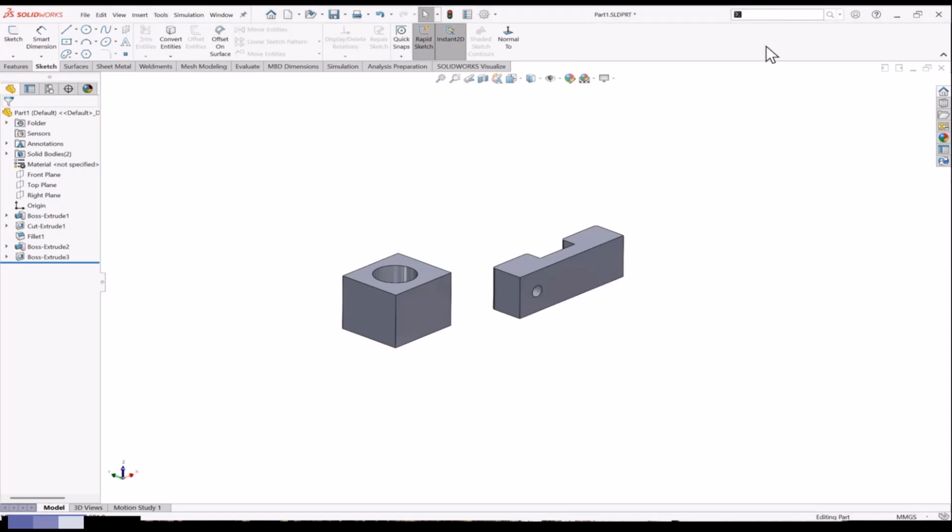The best way is, if you know the name properly, for example, I'll type a name which is not directly visible, like the split command. I'll type split. You see there? It will show you the remaining options that we cannot directly see on the screen. There are a lot of tools which are not directly visible. There are different places and we don't know where to go to take that. If you've seen that command anywhere, you know that command exists in the software. You can come and search here and you'll get the command. That is the easiest way to access any command.